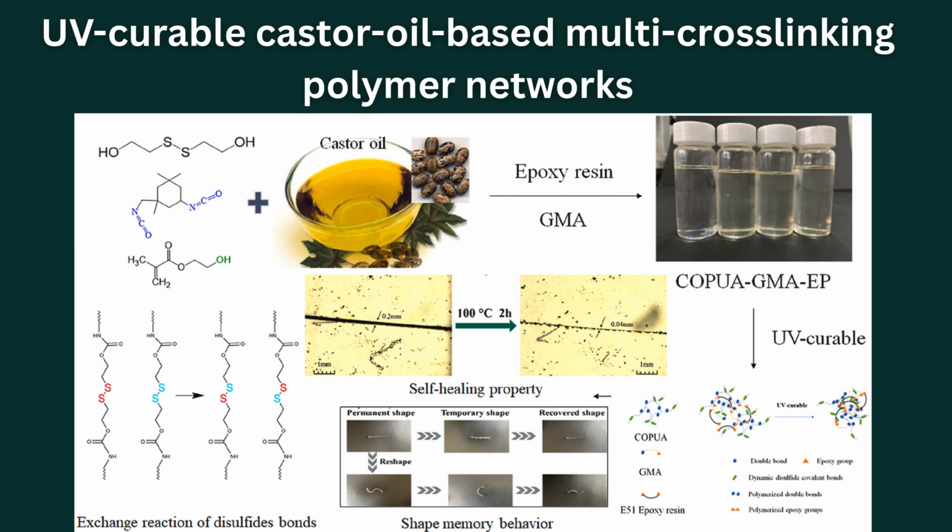Epoxy composites derived from castor oil represent a rapidly growing area of research. Interpenetrating networks of polyurethane and epoxy resins reinforced with nanofillers such as montmorillonite or carbon nanotubes exhibit enhanced mechanical strength, thermal stability, and damping properties. Even small amounts of carbon nanotubes can significantly improve energy dissipation through interfacial friction mechanisms.